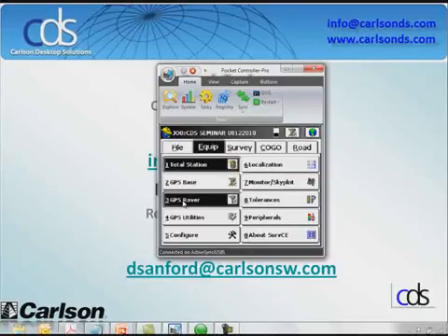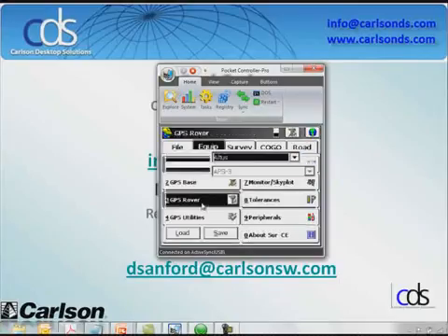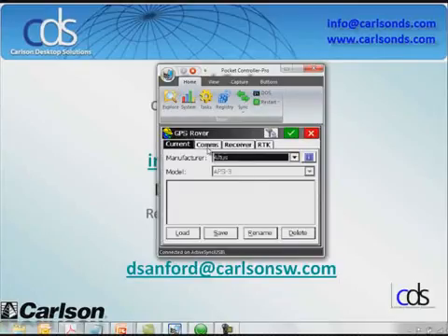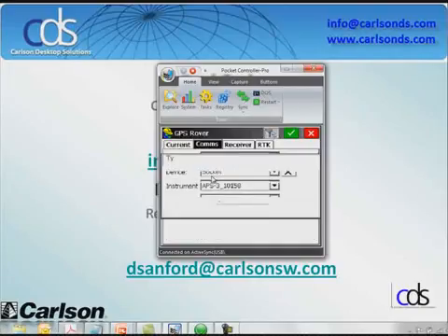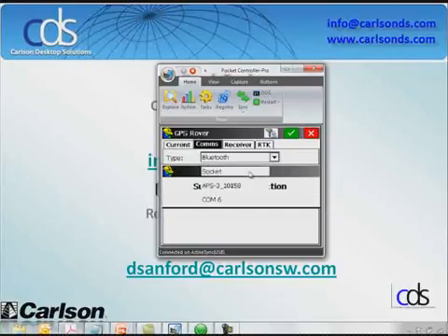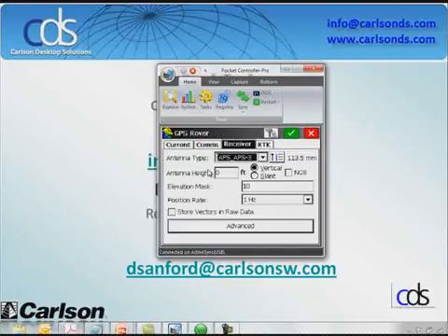whether we're on either device. So what I'm going to do now is configure the GPS rover. Again, I'm going to verify that I'm using the Altus APS-3, Bluetooth connected to that receiver. I'll click the bond with Bluetooth. We have a successful connection. My receiver option, same information here, my antenna height, the elevation mast.